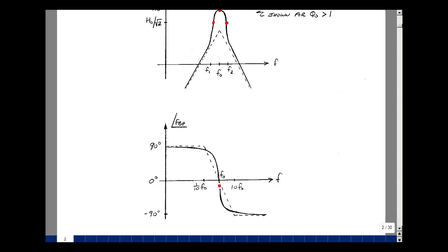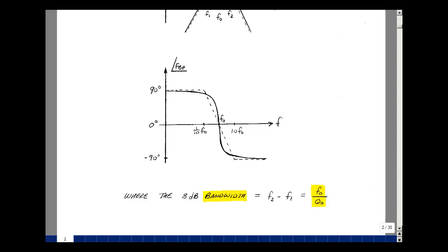If it's a negative number, you have 180 degrees. In other words, this whole curve is shifted by 180 degrees. So it's a very special result in terms of finding that center frequency. We're going to use that fact to actually tune in on our circuit.